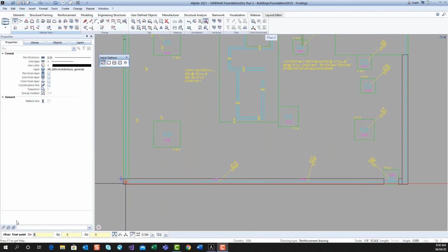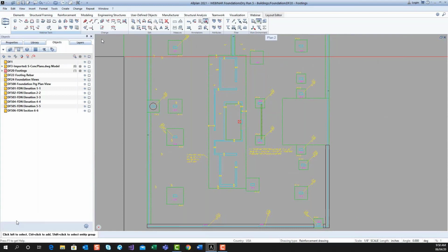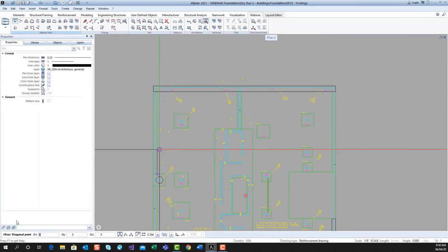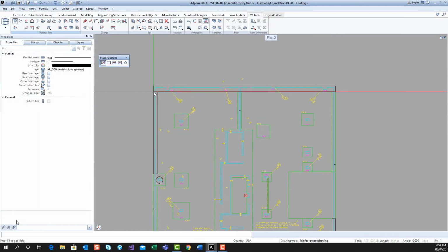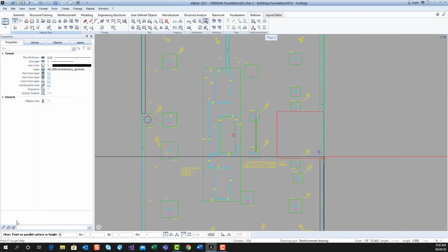As well as doing these simple boxes, there are other ways we can enter in our concrete information, which you'll see in a second here. We can do it with what we call Python parts. We can do it with elements. We have footing elements, slab elements, and so on. This allows us to very quickly get information here to start detailing, to start putting bar in.